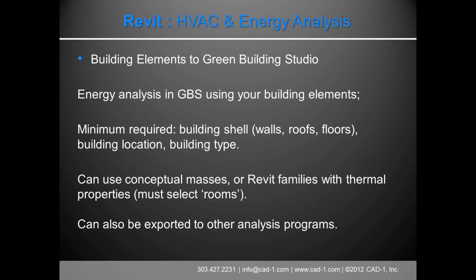And we can do that energy analysis with elements from your live building. And again, the absolute minimum that you want to have in there is the building shell should be enclosed, or at least very close to it: walls, roofs, floors, as well as the building location and the building type, which I just looked at in Revit.